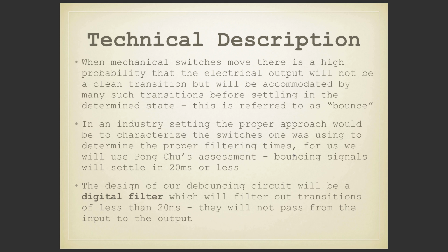If you were assigned this task in industry, most likely what you would do is purchase a handful of the switches that you're required to interface to. Then you would characterize them by taking them to the lab, measuring the duration of the bounce, then ensuring that the circuit you design meets the worst case behavior of your switches. For us, we're just going to accept Pong Chu's assertion that the bouncing will settle in 20 milliseconds or less.